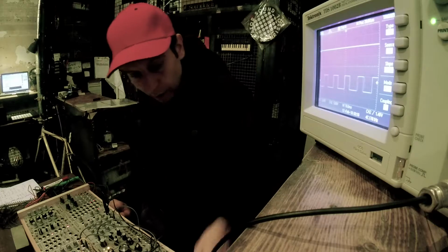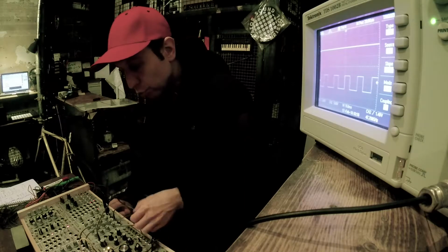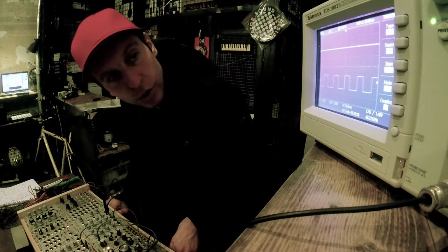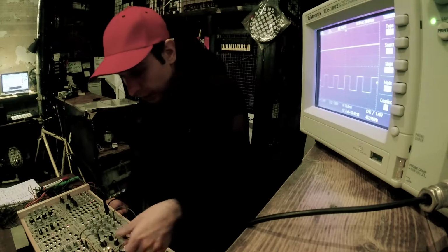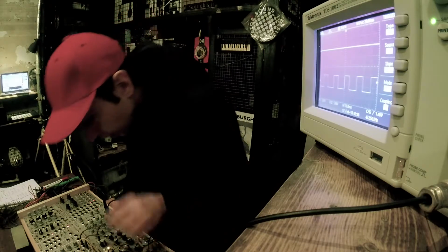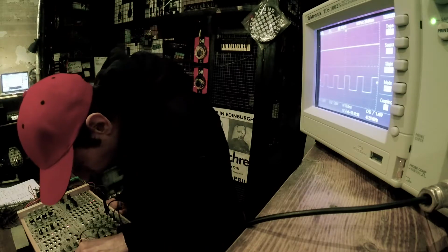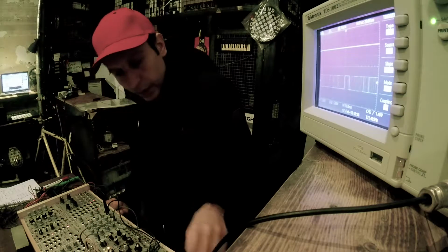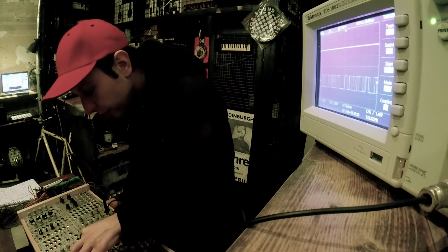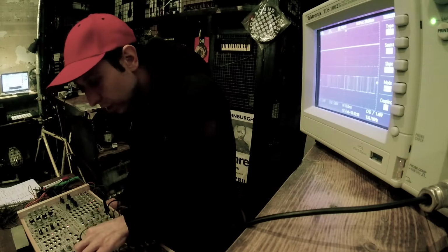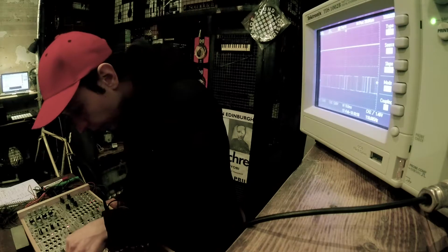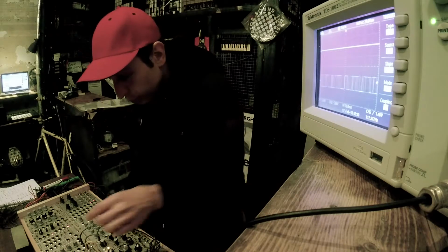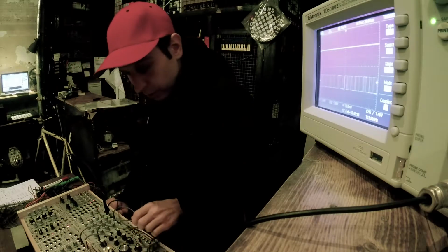Okay. Well, I would say that that's not huge as far as change in frequency goes. You see it's slightly wiggling. If I would want to increase that, I'm pretty much at the edge of it, so I think the 1 volt per octave input is better. I have two CV inputs for frequency on this oscillator. One where I can adjust the amount, and the 1 volt per octave input, which is a much more sensitive input as far as that goes.